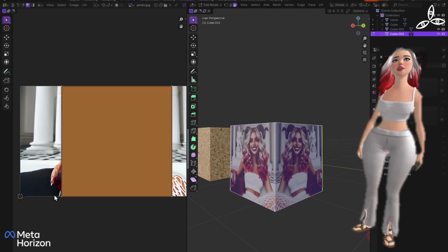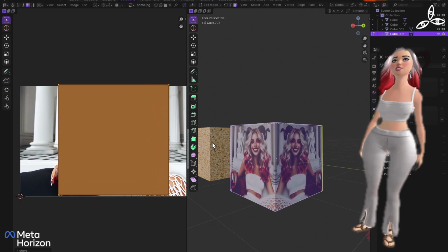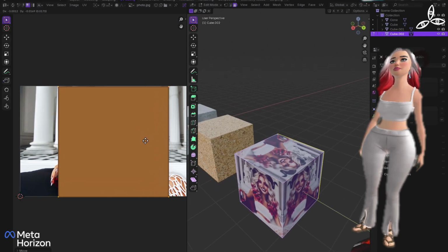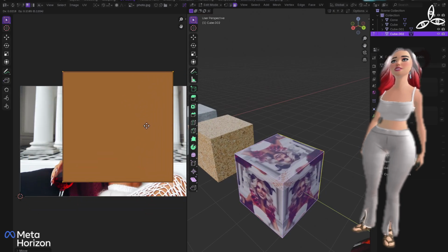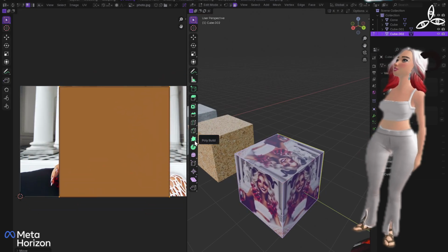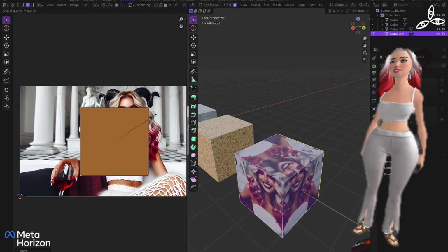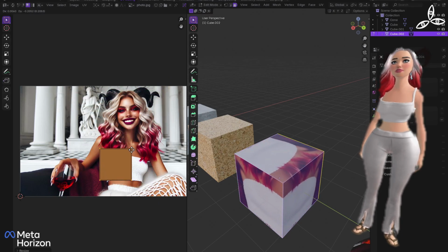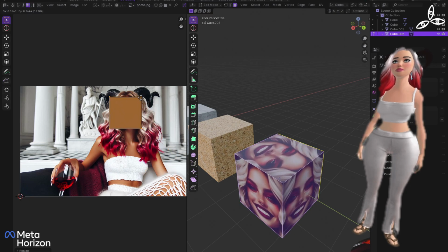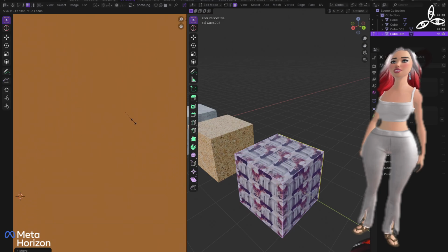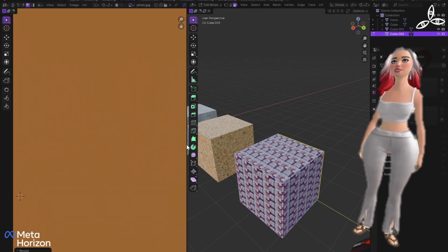If I just go back here, I'm going to select all these UV maps now. So that is basically all 6 sides overlapped over the same image. So if I press A in this window, I can press G and grab, and I can actually reposition that. And I'm going to just angle this so you can actually see it on at least 3 sides. Yeah, it's pretty cool. Likewise, and this is a bit like using the 3D viewport, if I press S, I can resize it. Look, so I can zoom in. Perfect. And also if I press S again and scale out, watch what happens.